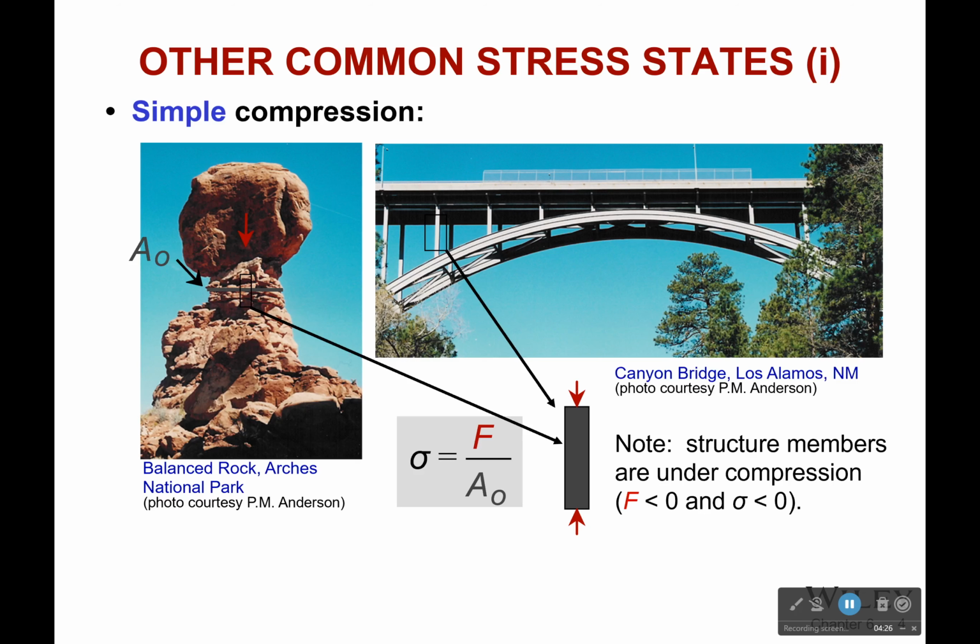Now, like I said before, we had tensile stress before. We also have compressive stress. And with compressive stress, it's the same equation. However, there's one key thing to remember. If they're under compression, the force is considered negative, as is the stress. Also, if they're compressed, they typically fail a lot later than with tensile.